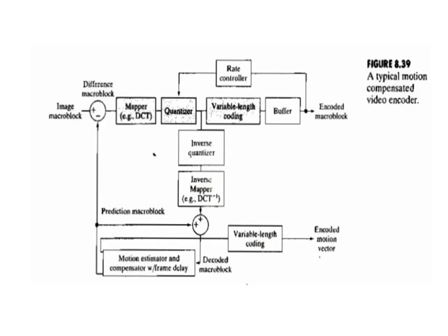This figure shows the typical motion compensated video encoder. It exploits redundancy within and between adjacent video frames, motion uniformity between frames, and the psychovisual properties of the human visual system. We can think of the input to the encoder as sequential macro blocks of video. For a color video, each macro block is composed of a luminance block and two chrominance blocks. Because the eye has far less spatial acuity for color than for the luminance, the chrominance blocks are often sampled at half the horizontal and vertical resolution of the luminance block.